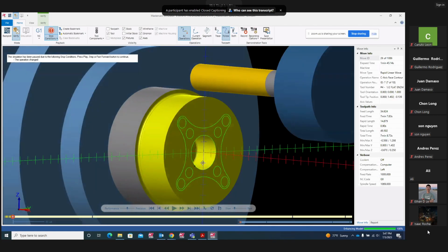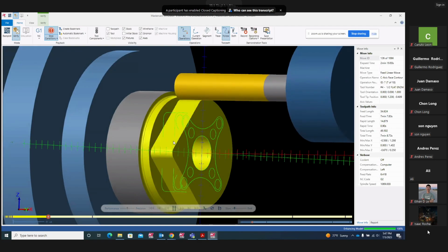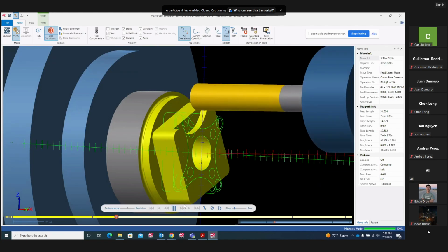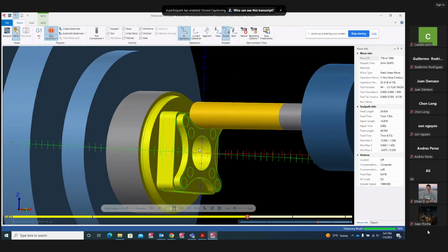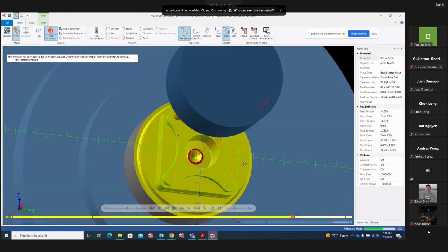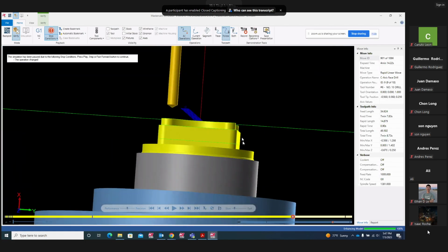And here comes my live tooling. Look at that. This is going to cut that geometry right here, the one in green, the rectangle. And if you look at here, that follows that geometry just like mill, guys. Look at that, just like mill. This is my Z0, and I can maintain my depth from here going down Z minus.